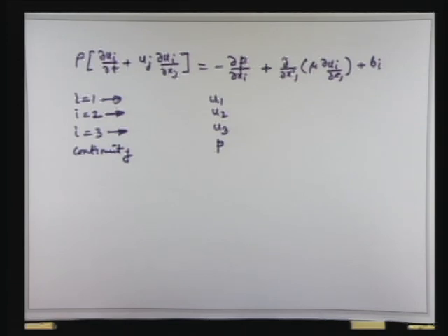And for that, you have to bring in what? You have to bring in the energy equation, which falls in the purview of convective heat transfer. So there may be additional equations necessary. If rho is a function of pressure and temperature both, you require an equation of state to describe rho as a function of pressure and temperature. So additional equations may be necessary to describe additional effects.